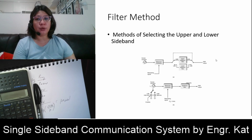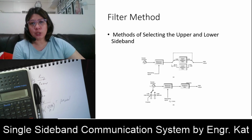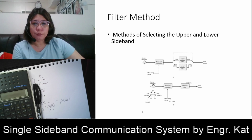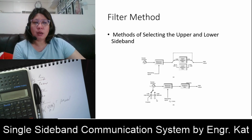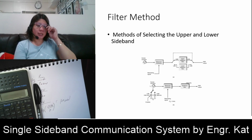There are two methods for selecting the upper and the lower sideband. Either we make use of two filters and just switch in between those two filters, or we make use of two different carrier oscillators. One carrier oscillator can produce the lower sideband, and another carrier oscillator can produce the upper sideband.